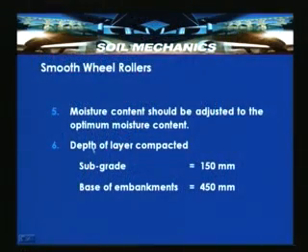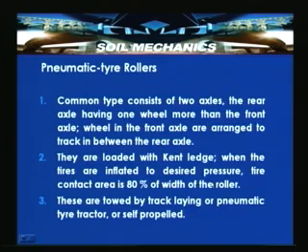The moisture content should be adjusted to the optimum moisture content, and the depth of the layer compacted is around 150 mm for subgrade and around 450 mm for the base of the embankment. So, this is about the smooth wheel rollers. There are also other rollers like pneumatic type rollers and sheep's foot rollers.